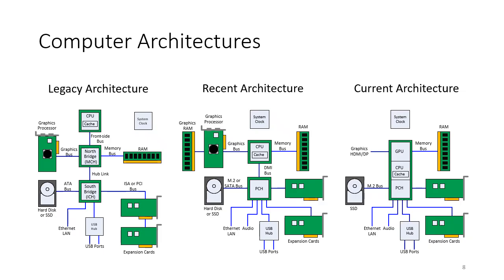The south bridge in later systems would also give you the Ethernet interface itself, but as I mentioned, in the older systems, it was a separate card. USB ports as well. When USB first came out, that would have been a separate PCI or ISA expansion board, but later built into the south bridge. And then the south bridge supported ATA, which is an attachment interface bus, and that was used for legacy hard disks, and later for SSDs, but SSDs came along a lot later.